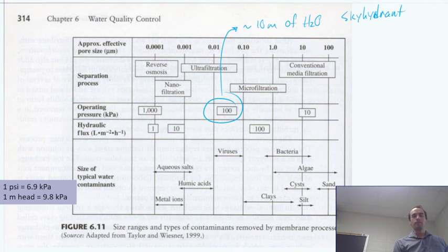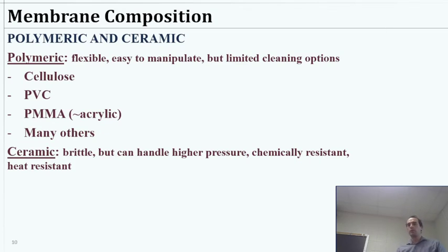Kind of a deal. Okay, and with reverse osmosis, we're really getting to the point where we have membranes selective enough to get rid of those aqueous salts with the ions that we would be dealing with. We can also use that, and maybe we could call it nanofiltration, to get rid of some of the larger metal ions. So if we really wanted to, we could probably deal with arsenic, for example, with membranes. Usually there's cheaper ways to do that with oxidation and precipitation.